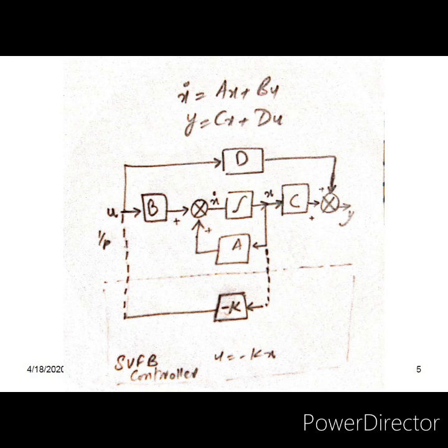That is our concern. And we want to design this in such a way that the closed loop poles of this system, shown here in this slide, become equal to the desired poles. We set the target, called the desired poles, and they are determined on the basis of some performance requirements such as the rise time, settling time, overshoot, undershoot, etc. On the basis of that, some targets are set. We can talk about that in the upcoming lectures.